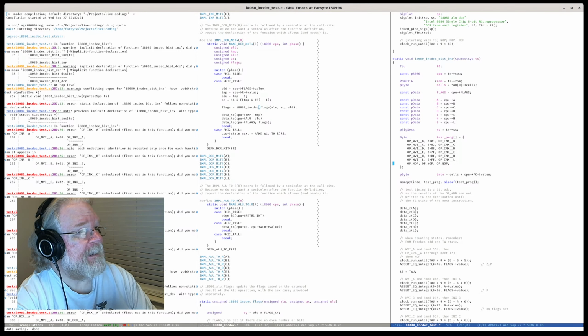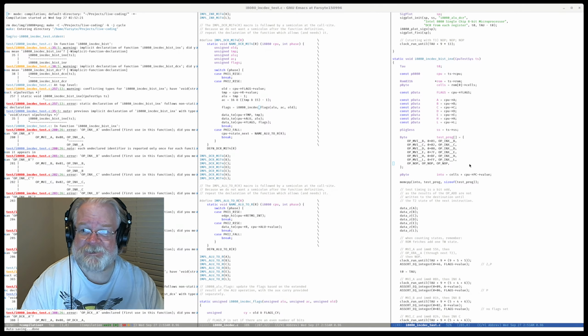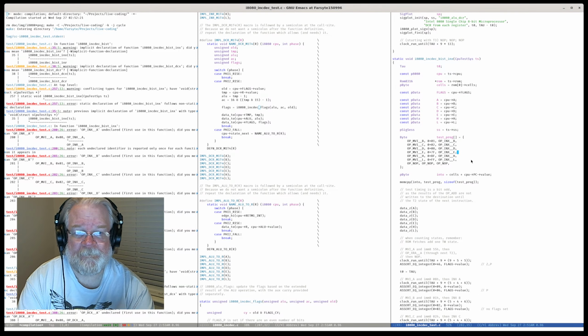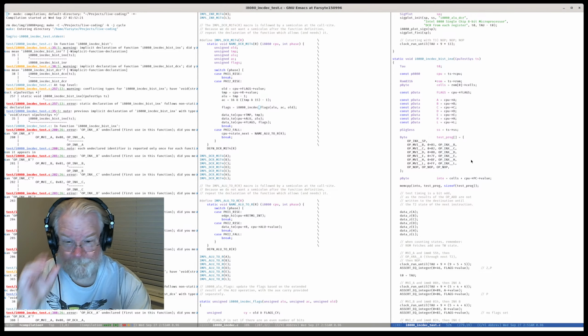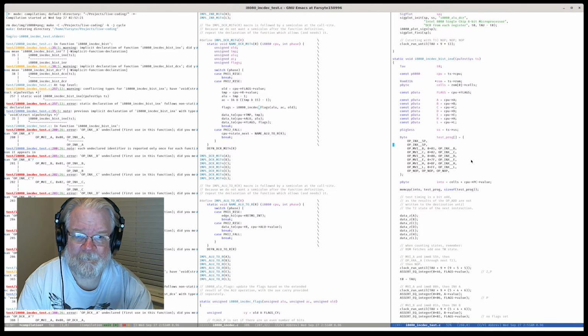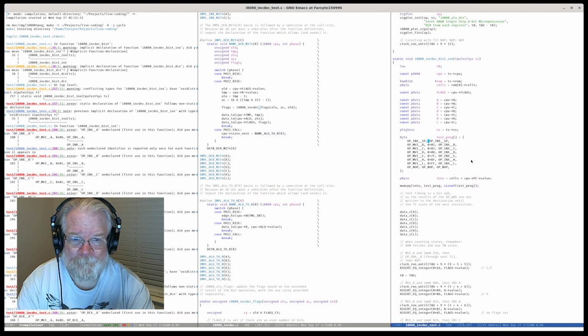What do I want to do in a way to set the stack pointer? I will have to set it manually from the simulation by manipulating the state of the register because I don't have instructions to do it yet. So we'll do that right off the top. And what I'm going to do is increment the register pairs twice. So what I want to do is make sure that I can see both registers do something.